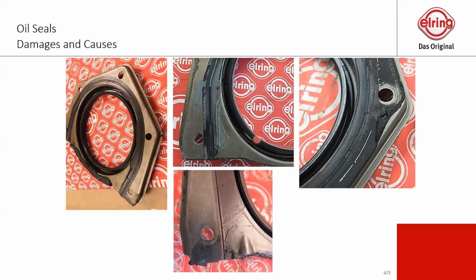That means this elastomer is pressing against and needs the flexibility to work in any kind of temperature and vibrations and so on. So they need space to work. What is not recommended, as you see here, is to use any kind of silicone RTV to be on the safe side, to make a better sealing job, because in this case you will not support them, you will work against them. This is the point.